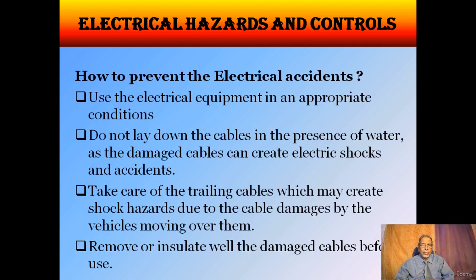Now we will see how to prevent electrical accidents. Use the electrical equipment in appropriate conditions. So you should take care that you use the electrical equipment in appropriate conditions only. Do not lay down the cables in the presence of water.